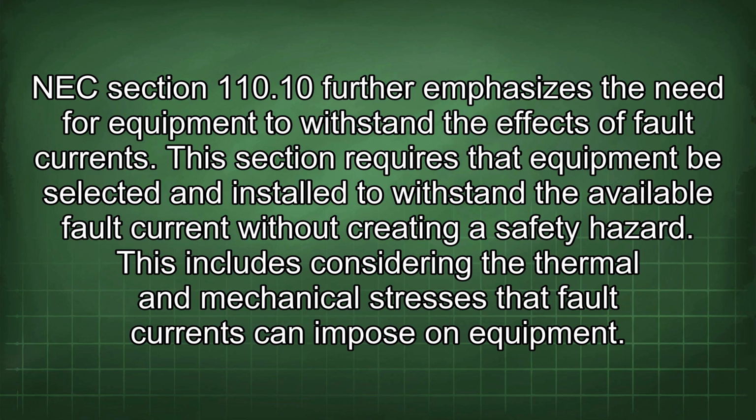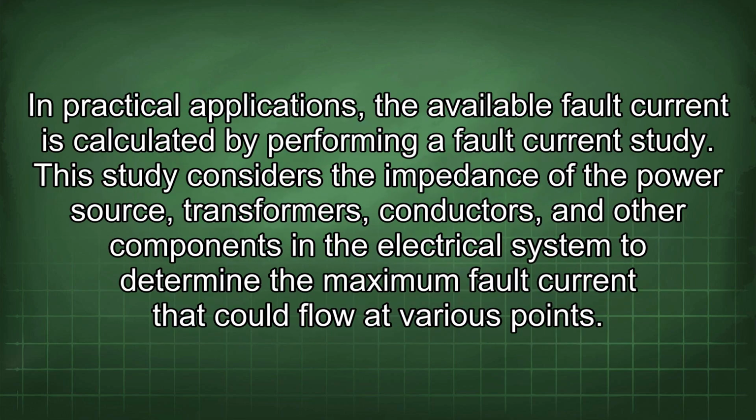NEC Section 110.10 further emphasizes the need for equipment to withstand the effects of fault currents. This section requires that equipment be selected and installed to withstand the available fault current without creating a safety hazard. This includes considering the thermal and mechanical stresses that fault currents can impose on equipment. In practical applications, the available fault current is calculated by performing a fault current study. This study considers the impedance of the power source, transformers, conductors, and other components in the electrical system to determine the maximum fault current that could flow at various points.